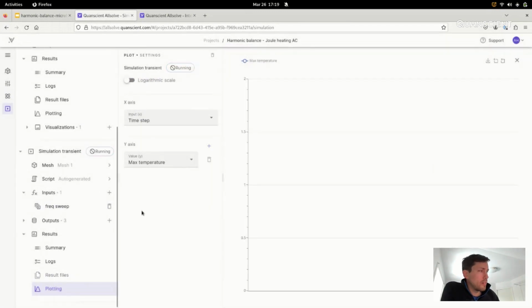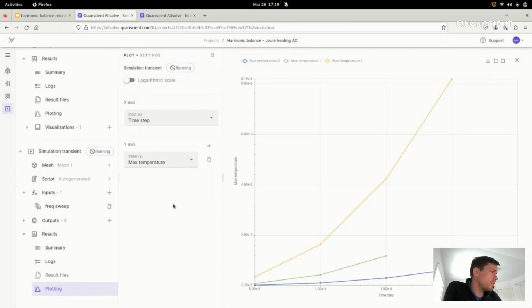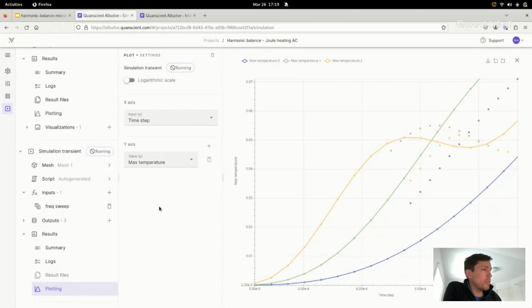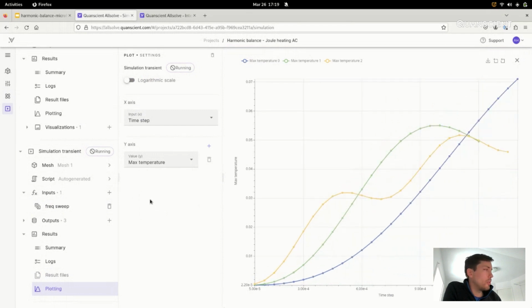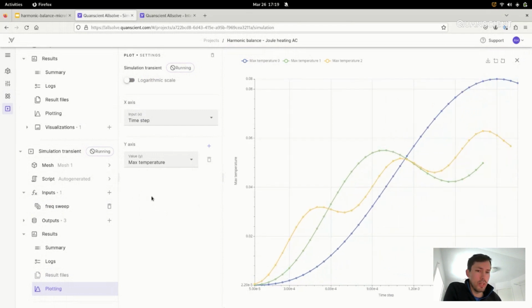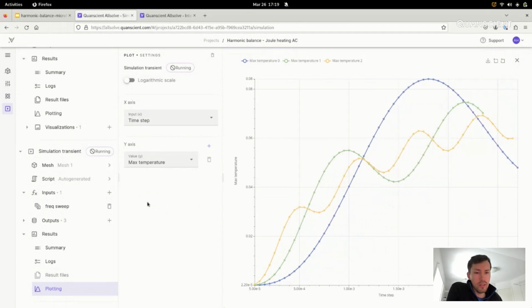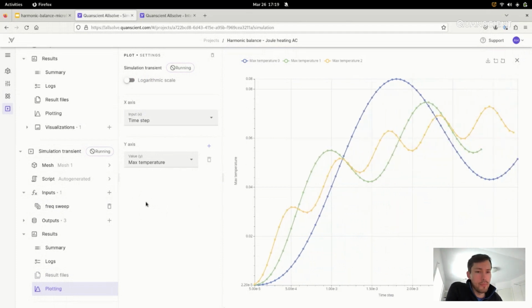you have a transient, as I just showed in the slide. And then basically for the higher frequency, you will see that the swing around a static heating is the lowest, and the higher the frequency, the lower the swing. But the lower the driving frequency, the longer the cable has to cool down, and so the higher the swing.